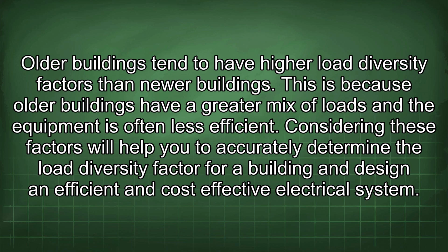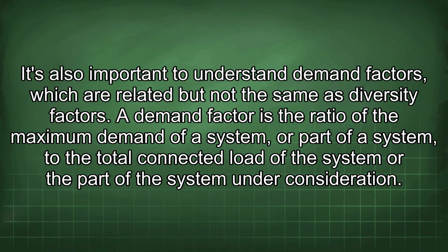Older buildings tend to have higher load diversity factors than newer buildings. This is because older buildings have a greater mix of loads and the equipment is often less efficient. Considering these factors will help you to accurately determine the load diversity factor for a building and design an efficient and cost-effective electrical system.